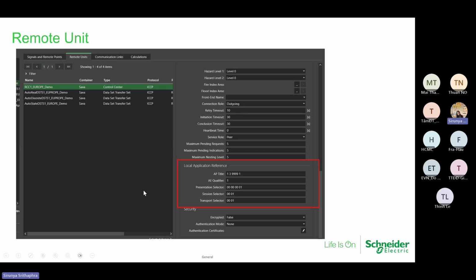Yeah, so that's it. But I think the other thing they're saying, this ADMS has 4 servers, right? Yes. And all of those can be an ICCP server? They just run in a redundancy setup, because you only see one server active at a specific time. The others are waiting, and if the active server collapses or something like that, it goes to the next active.